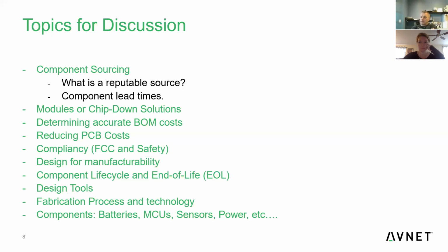So there's a couple things you could do. If you ask for the paperwork, they should be able to produce it, and they should very willingly produce it. The other advice I would give you is make sure that the paperwork is applicable to that actual part you have. So make sure it explicitly states the part number that you're using, because I have in some cases seen people get paperwork that looks great, but it doesn't reference that exact part number, and in that case it's not applicable.